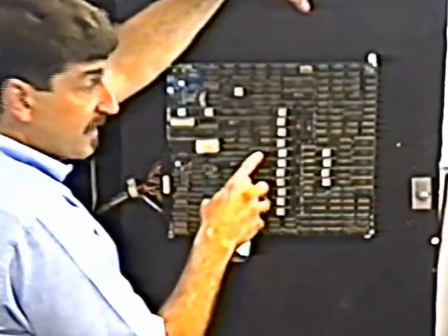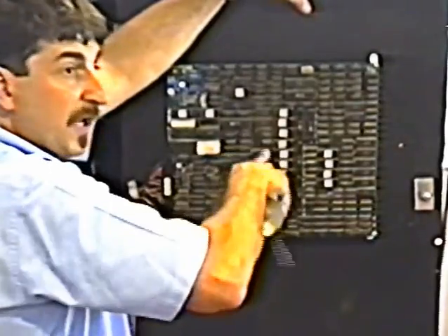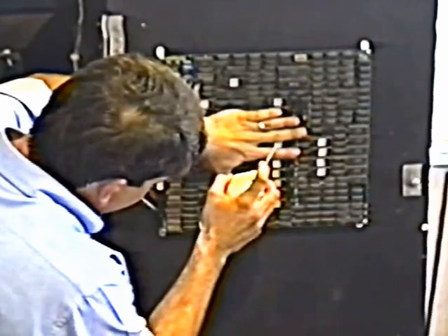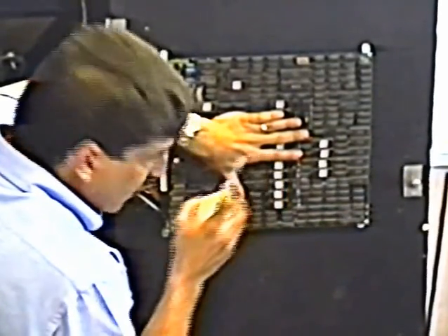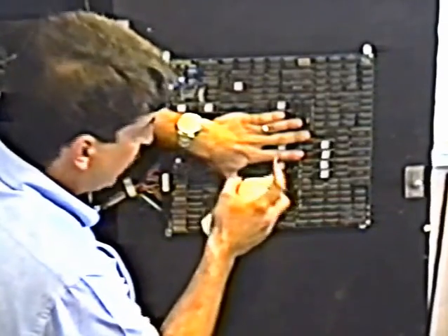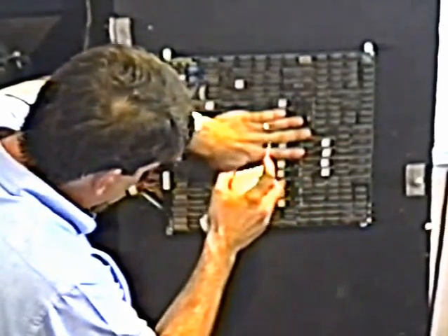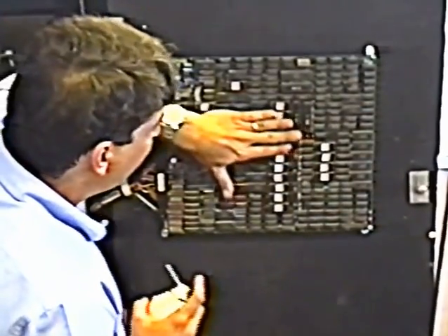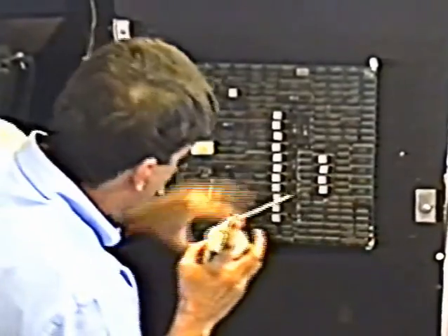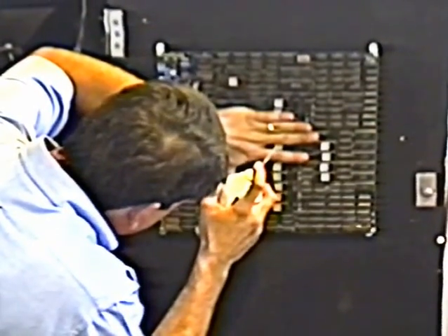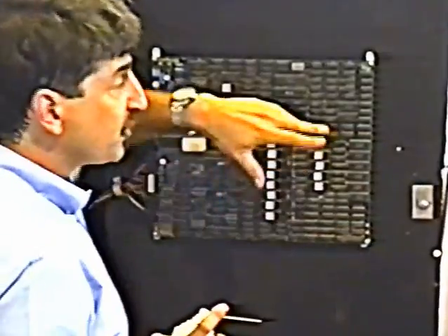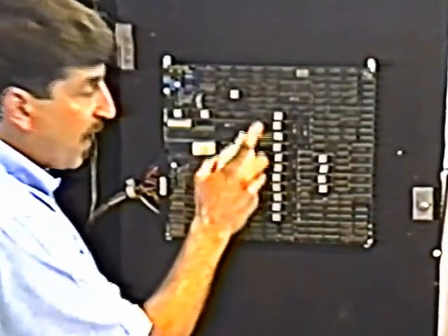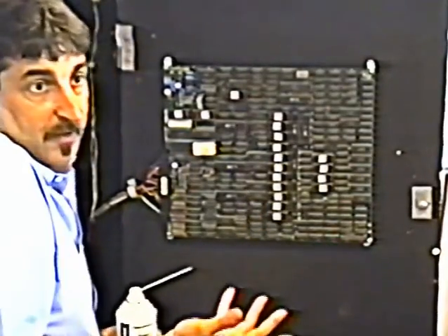Now, you may have found the right IC, you may have not found the right IC. Heat it up again with a hair dryer. Temperature cycle it many times. What I often do is I'll cover up the adjacent chips with my fingers like this, and barely hit it. While you're up here, if you've got a wart or something, just go ahead and freeze that baby right off. Just hit it. Okay, problem goes away. Get the hair dryer out. Heat it up. Oh, problem occurs. Make sure that you are just hitting that one chip that you think is bad. Temperature cycle it 5 times to make sure that that's the chip, because it's real easy to overspray and hit an adjacent chip and cool that one off simultaneously.